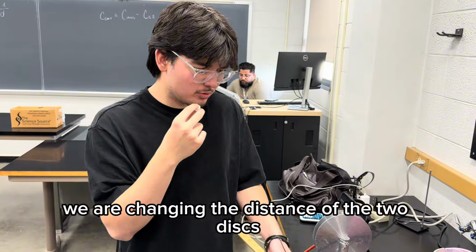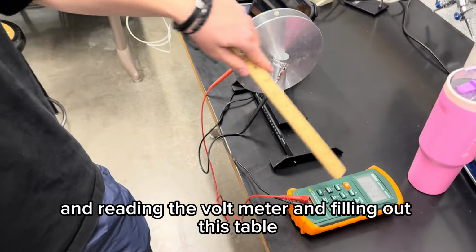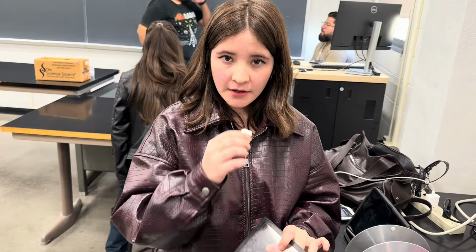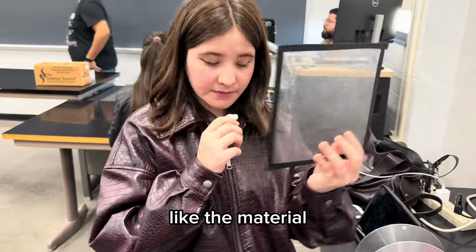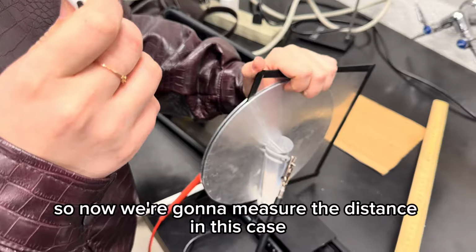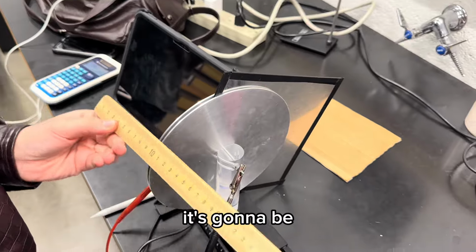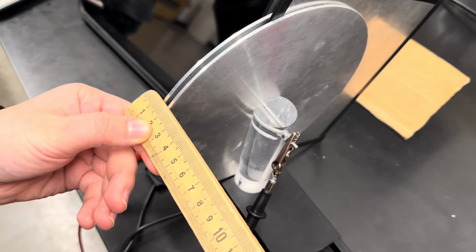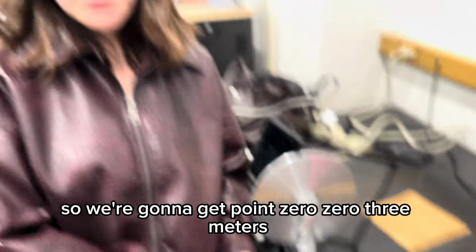For step 1, we are changing the distance of the two discs and reading the voltmeter and filling out this table. For the second step, the first thing we need to do is get the material and put it between the parallel plates, like that. Now we measure the distance. In this case, it's 0.3 centimeters, and converting it into meters we get 0.003 meters.